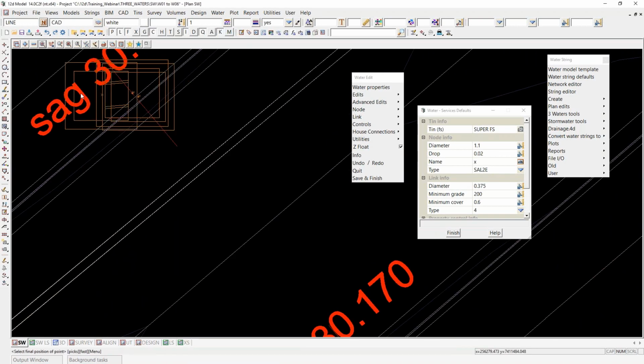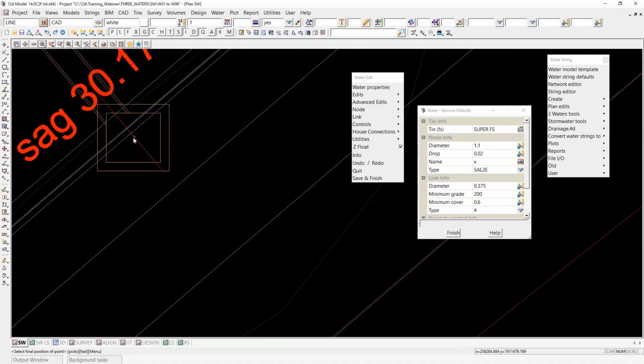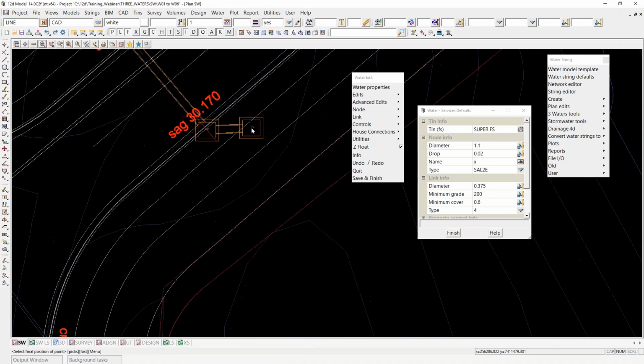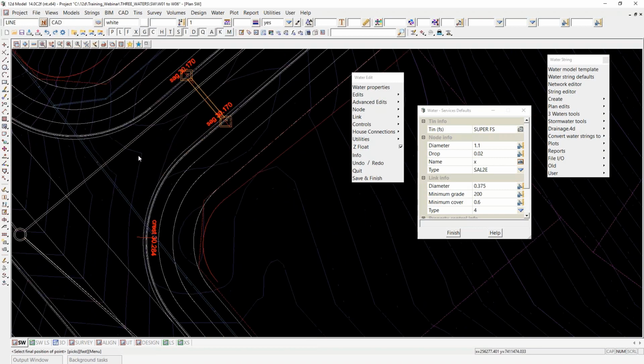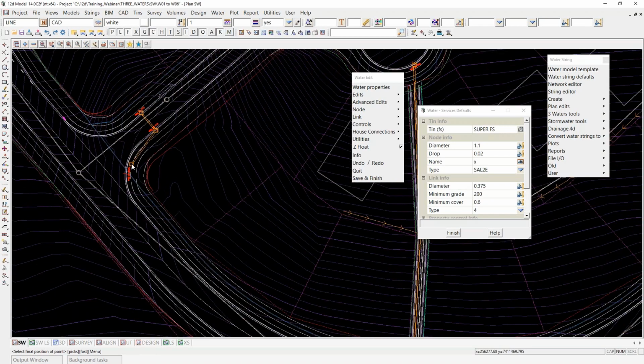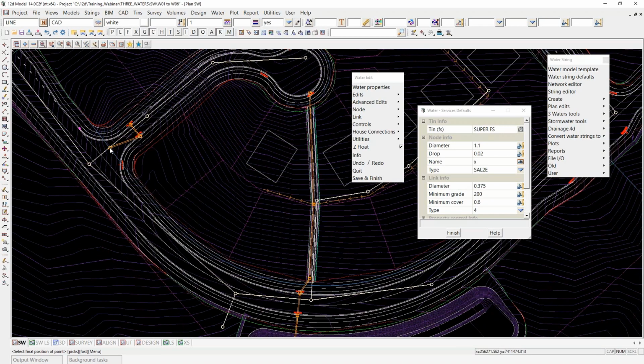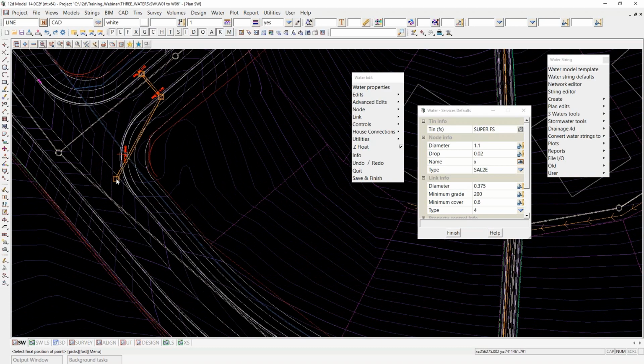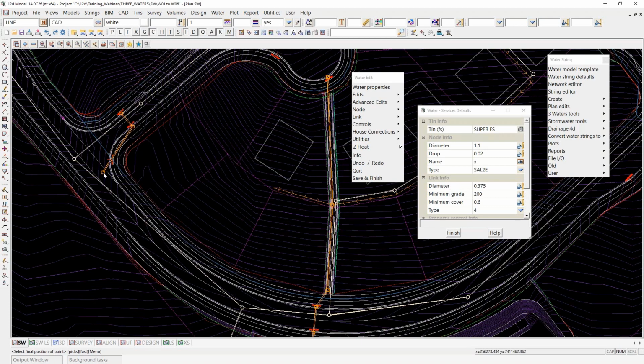Okay, again, I'm going to do a similar thing. I'm going to snap to the red sag markers here, and this is an approximate location of where the center of the node should be for these particular node types. And then how to turn the corner then, because I do need to keep my pipes in the road reserve here, but I also want to be mindful of the sewer line and the water line here in cream and blue respectively, and I don't want to sort of design a string on top of that. It can cross it, but I don't want to cross it at a very acute angle or anything like that.